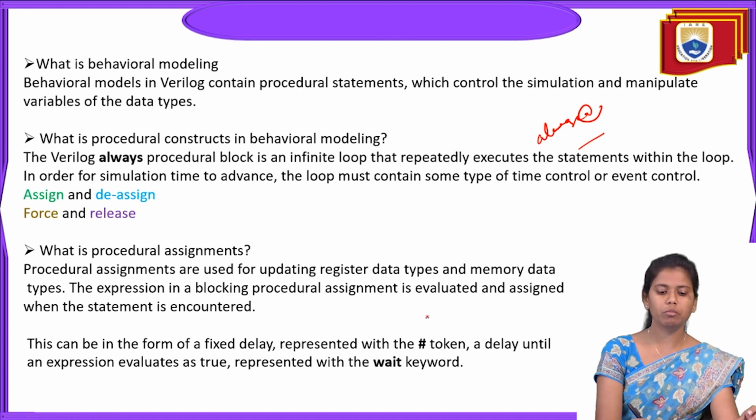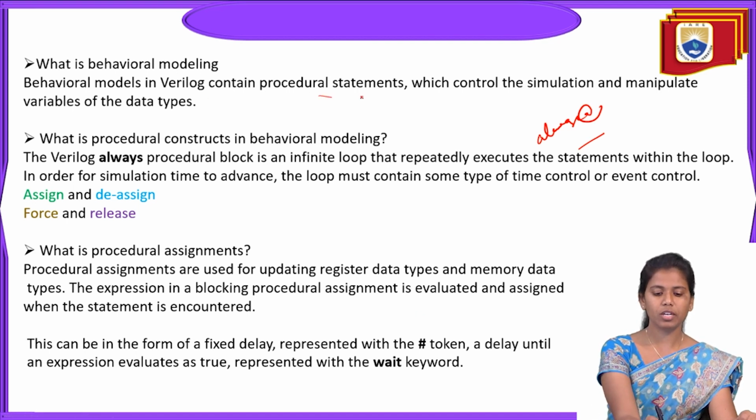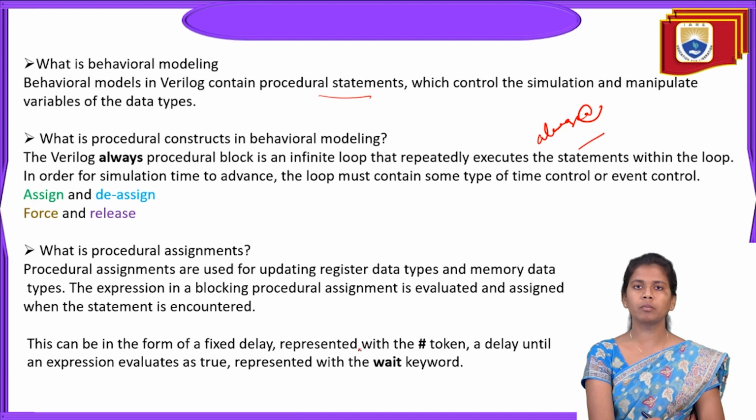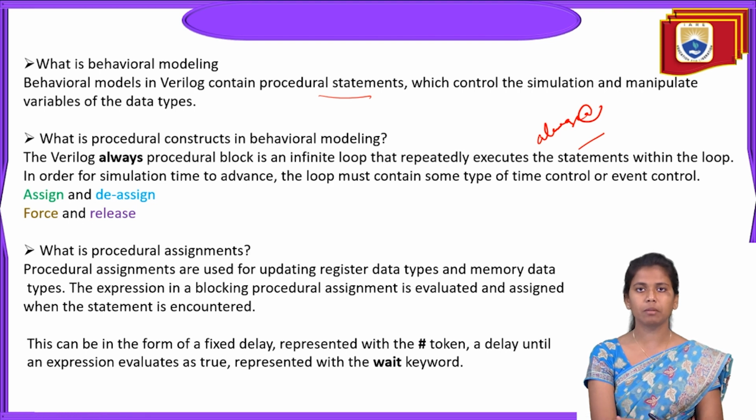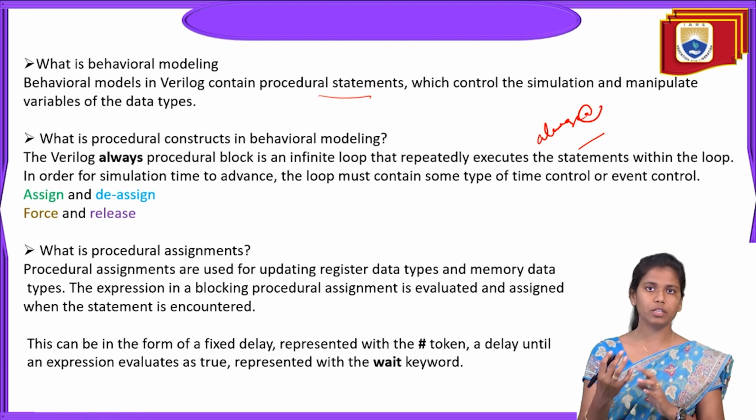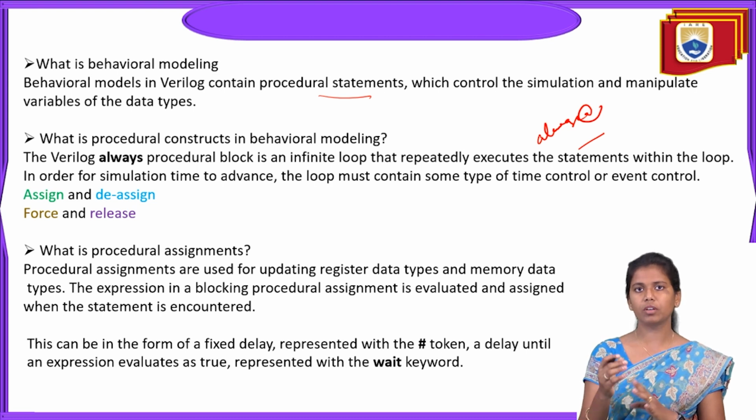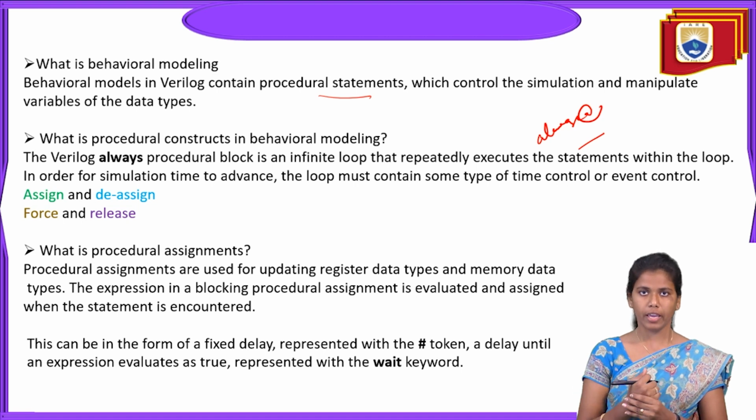Behavioral modeling in Verilog contains procedural assignment statements. We have come across different types of statements, and each statement consists of some assignments. The assignment statement has, to the left of the assignment operator, the variables to be declared, and to the right of the assignment operator, we need to mention the expression.